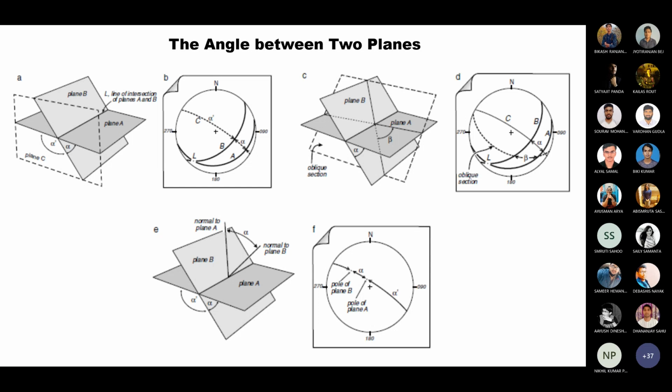Fine. So in this way, you can measure the dihedral angle between a pair of planes stereographically. You should remember that in order to do that, there are two angles that could be measured at this stage. These can be labeled alpha and alpha naught, the acute and obtuse dihedral angles respectively between the pair of planes, and if you add these two angles up, they give the value 180 degrees.